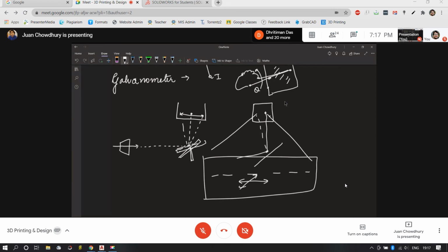Now these mirrors are silver based, and a very thin film of silver is used, extremely light, with no inertia, which means they are so precise and so easy to control by the sheer controlling of current and nothing else. You change the current level by microamperes, you get a deflection resolution of around 0.003 degrees, something like that.